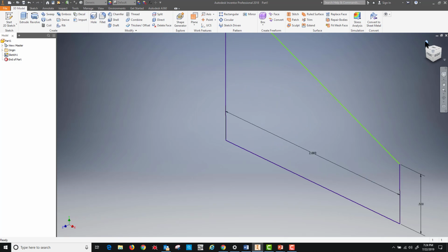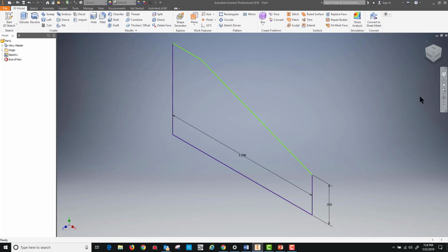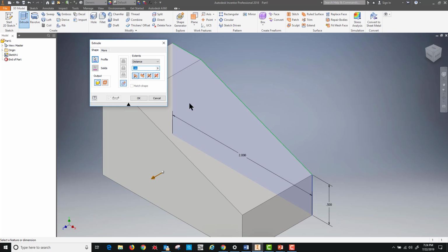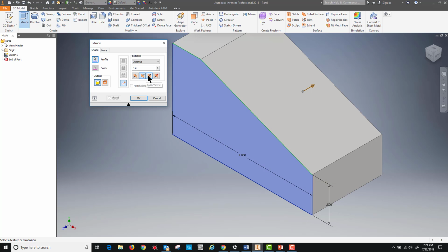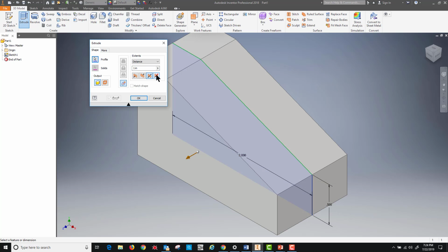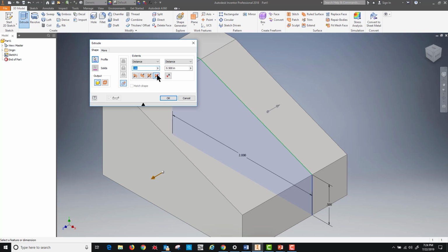And if we'd like for it to zoom in the window, we can actually go up to home like we were using before. It'll show us in the home window and it'll zoom to fit to where it's easier to see. At this point we have several options we can do. We can extrude this, and you're going to notice it'll automatically give us a few more options. We can extrude it out, we can extrude it back, we can extrude it in both directions, or we could choose one direction more than the other if we would like to.